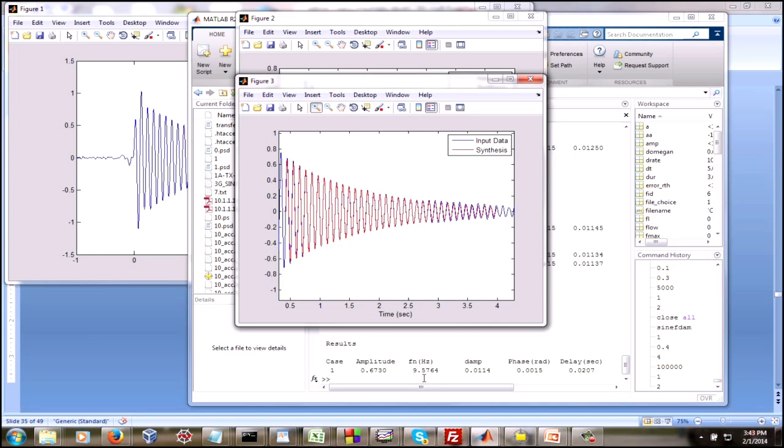A couple other things to think about is this is the natural frequency of the fundamental bending mode during drop transient. Well, what's going to happen during powered flight? Well, during powered flight, mass is going to be expelled. And when mass is expelled, then the total mass decreases, and the natural frequency is going to increase with time. So anytime we're looking at a launch vehicle, we want to know what the natural frequency is right as it's being launched, and also, actually for one that's ground launched, we'd want to know the natural frequency while it's on the launch pad, because we have to do wind and earthquake analyses.